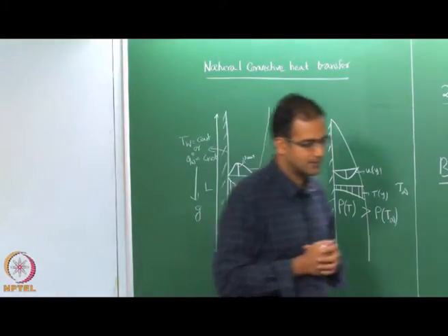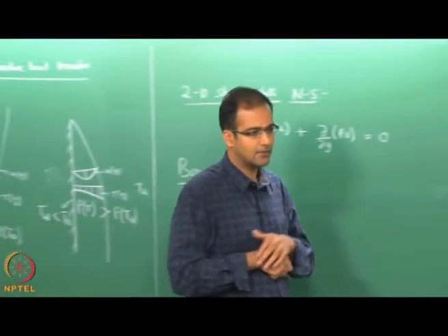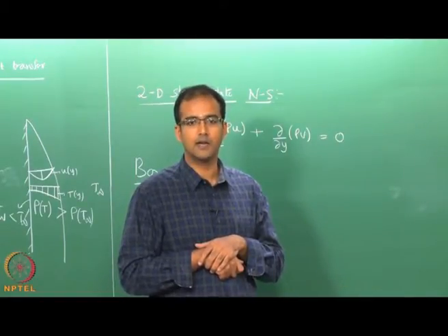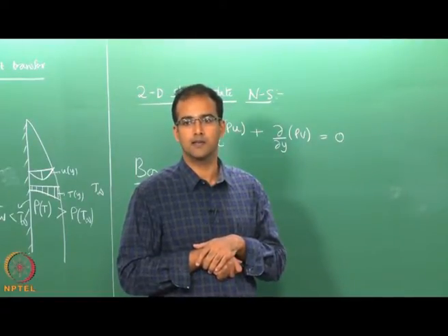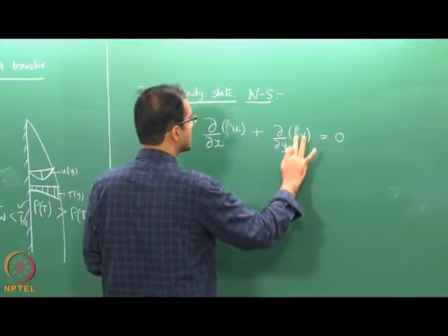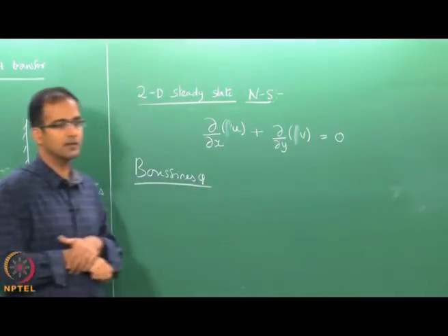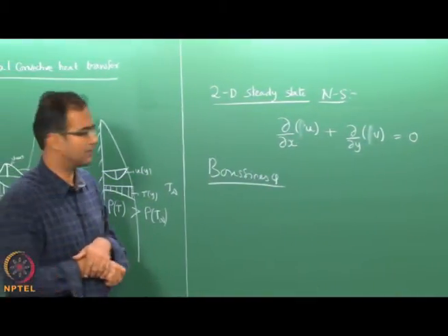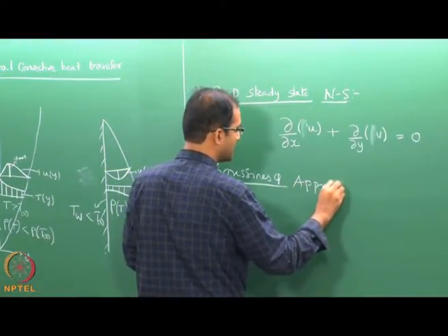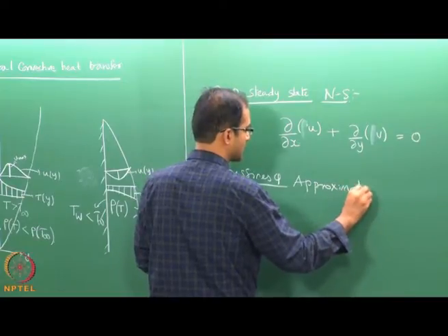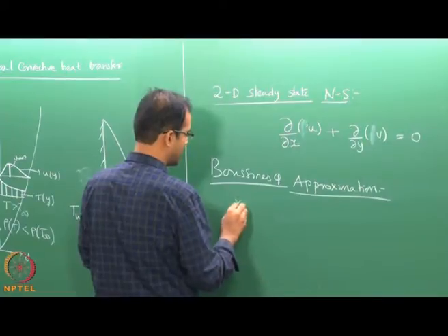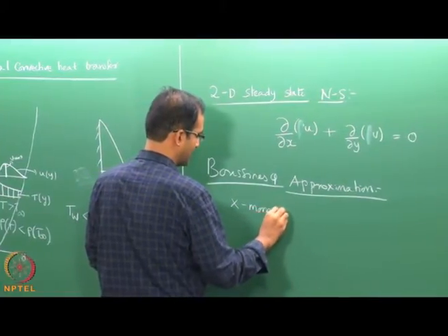So, to start off, we will make an approximation as done by Boussinesq and therefore try to pull density outside as a constant from the continuity equation, and also the convective part of the momentum equation. So, if you write down the x momentum and y momentum invoking the Boussinesq approximation, let us first write down the x momentum equation.